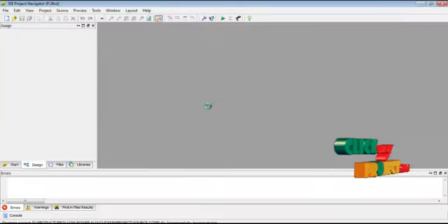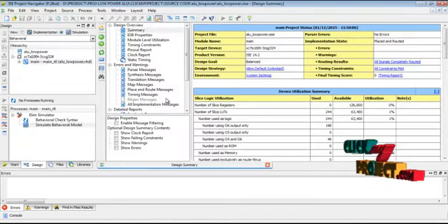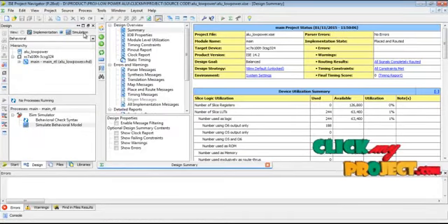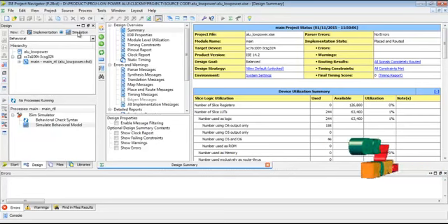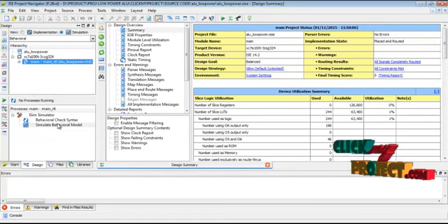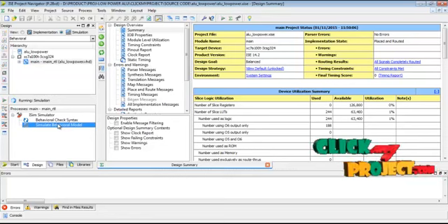This ISE project navigator is mainly used to do simulation and synthesis processing for our ALU processor. Then we select the simulation process and the main RTL functions, and click simulate behavioral model.